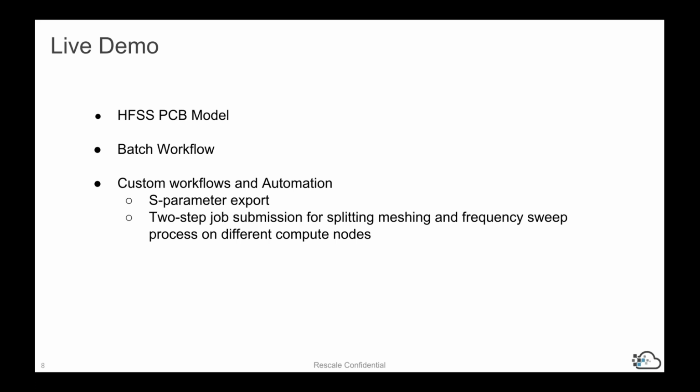The software we are going to use today is called HFSS, which stands for High Frequency Structure Simulator. It is a 3D electromagnetic solver, and today we are going to run the simulation and look at S parameters. The workflow that we are going to start with is a batch workflow, or a non-GUI workflow, in the sense that we have our input file and then we are going to run it on the cloud.